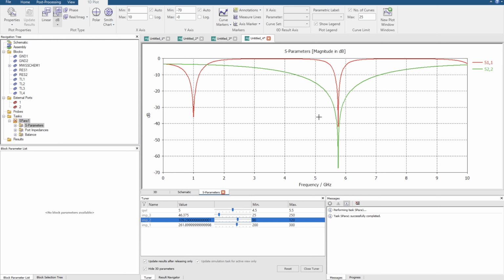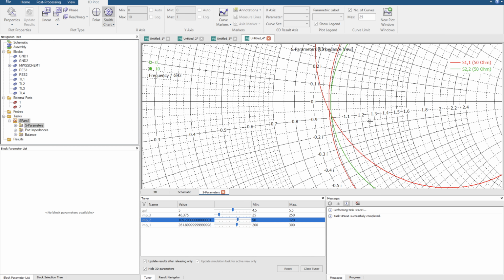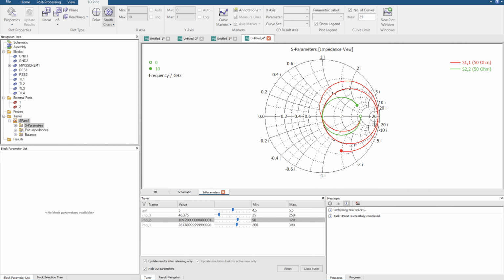So, you know, that's the benefit of using the Smith chart to match. You can kind of have a better understanding about where the Smith chart lines with respect to frequency. Because remember, you can go from this point here, which is your 10 gigahertz, and it's swirling all the way around back to where it's ending off at DC.